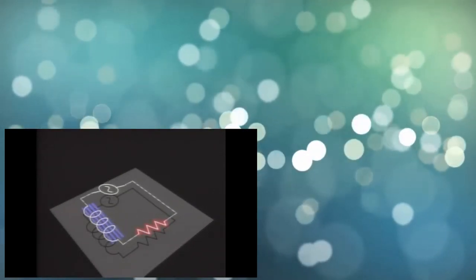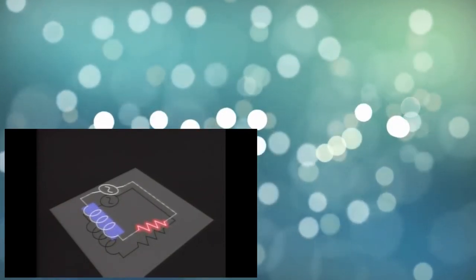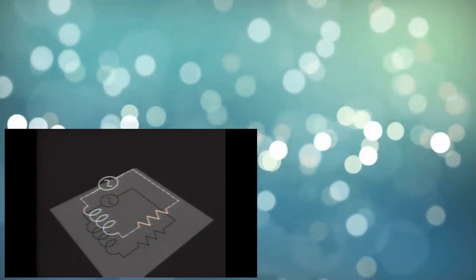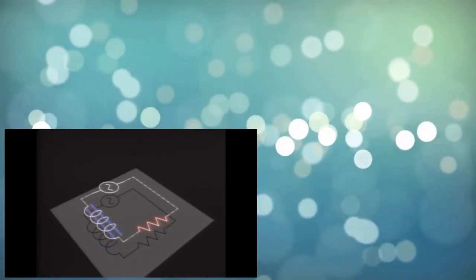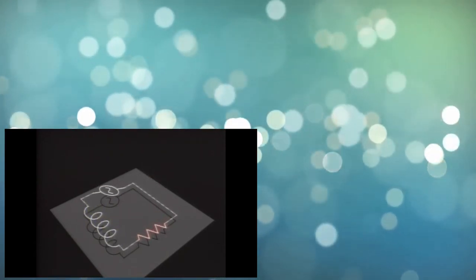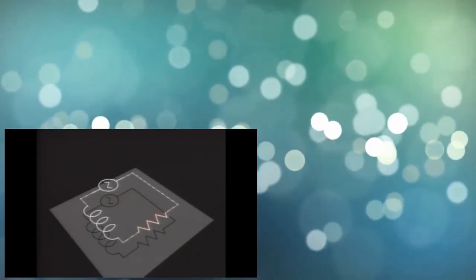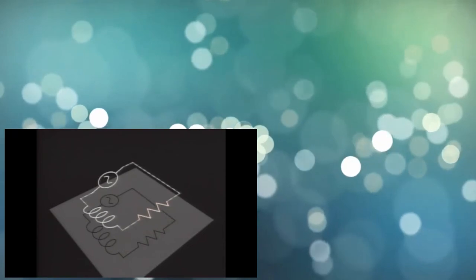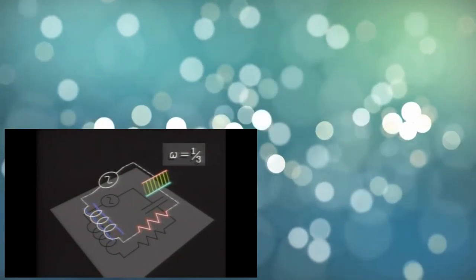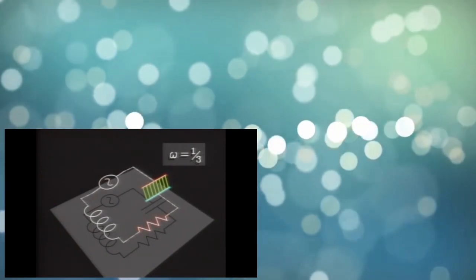On the other hand, if an inductor's in the circuit, at low frequency, there's plenty of time to build up current in it without much voltage across it. But at higher frequency, the current in the inductor can't change fast enough before it has to turn around. So the voltage is mostly across the inductor, and there's not much left across the resistor. When all the elements are in the same circuit at low frequency, most of the voltage goes into charging and discharging the capacitor.